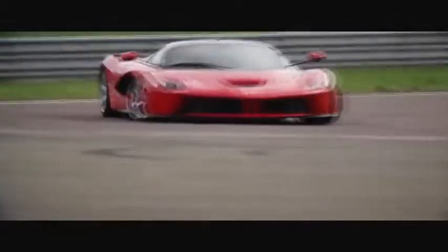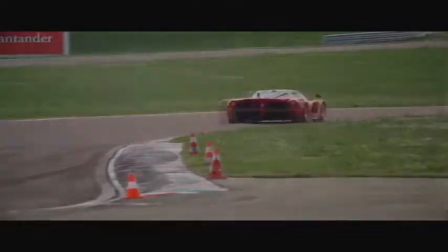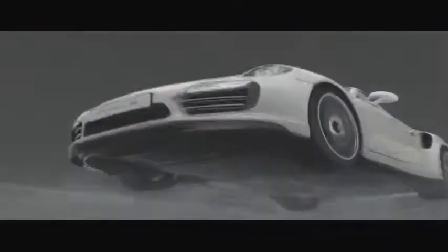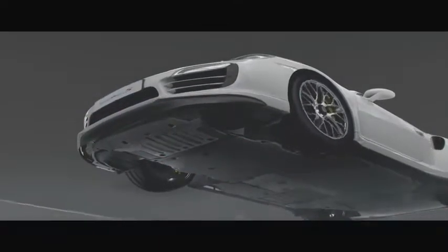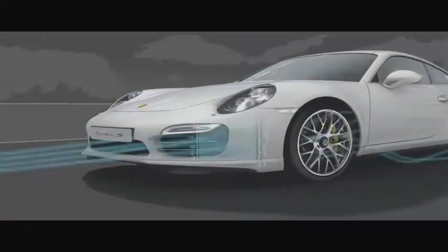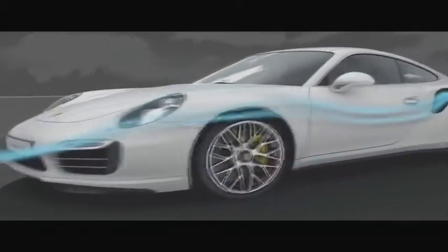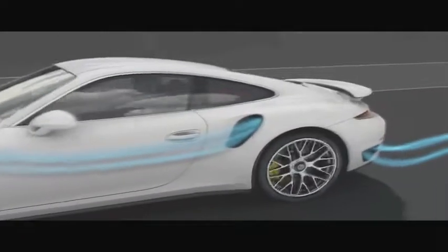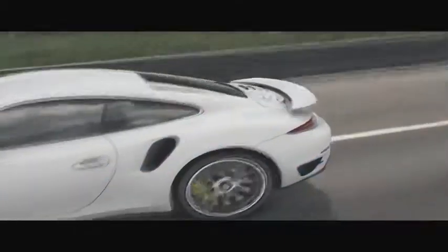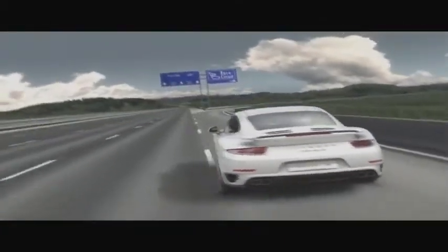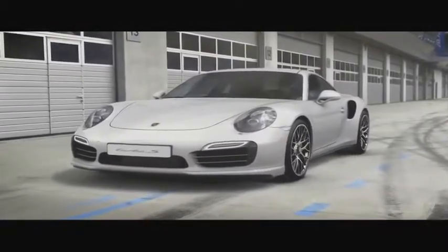In a lot of the stuff we covered, like spoilers and whatnot, vortex generators, those things are set to have a sweet spot and be most performance friendly at a specific speed. With active aerodynamics, the aim is to be able to adjust the angle of attack and height of the spoilers, splitters, and even canards. Anything really that comes in contact with the air is basically allowed to move and change its angle and position to basically create the lowest possible drag coefficient for the vehicle at just about every single speed above a reasonably high speed.